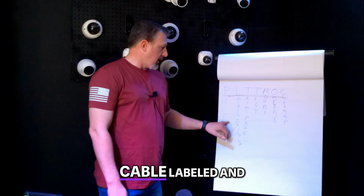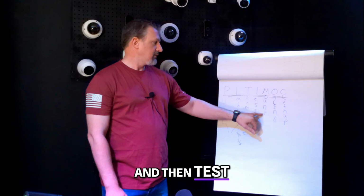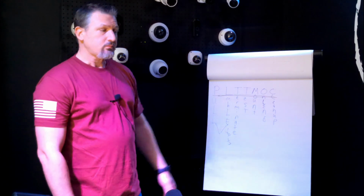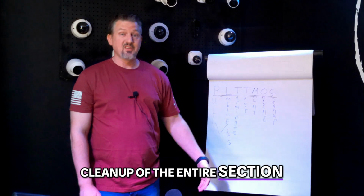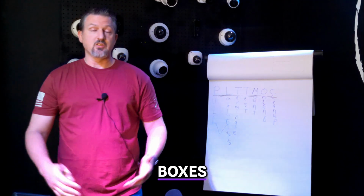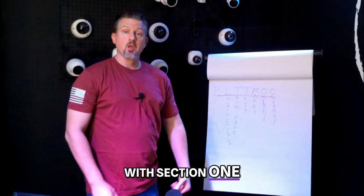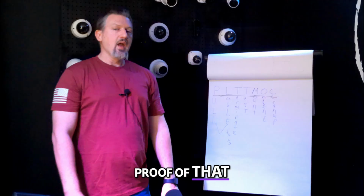Once we've got the cable labeled and pulled, we're going to then terminate and then test, then mount the device, pull them online. And when we pull them online, if it's a camera, we want to also adjust the field of view. Once we've done that for the entire section, we're going to do the cleanup of the entire section. Ceiling tiles put back. The floors are going to be swept. The IT closet's going to be cleaned up. Boxes, material, everything's going to be moved out of section number 1 because we don't want to have to come back to it. After we've done that with section 1, we take pictures, we take a video to make sure that it's all been cleaned up so we have proof of that, and then we can move on.